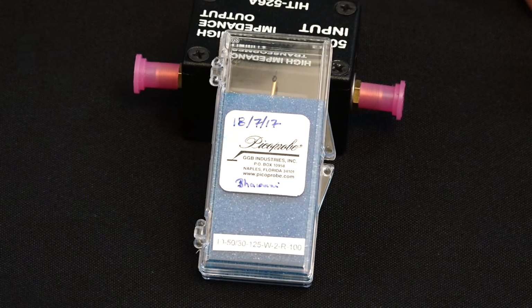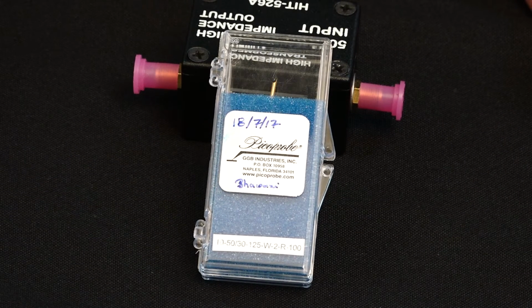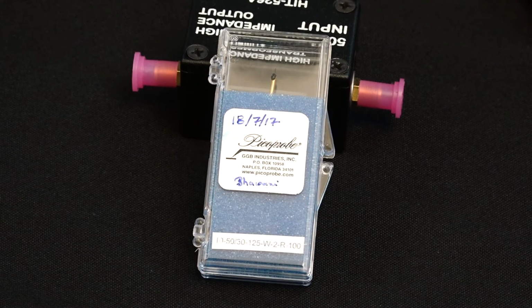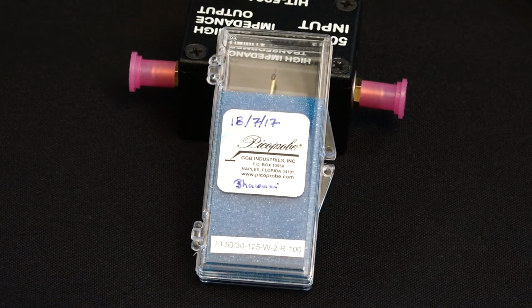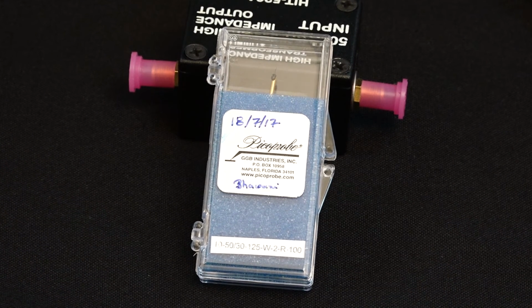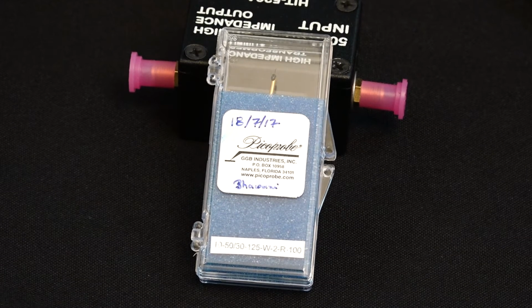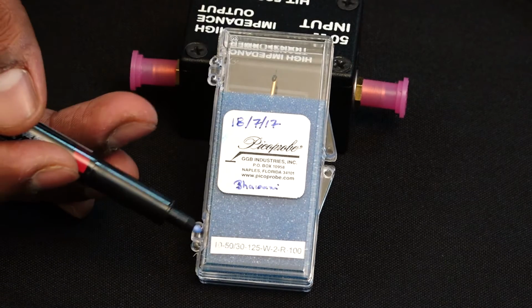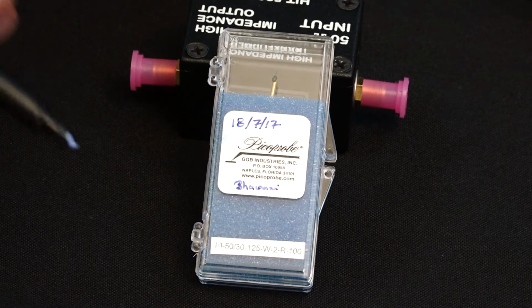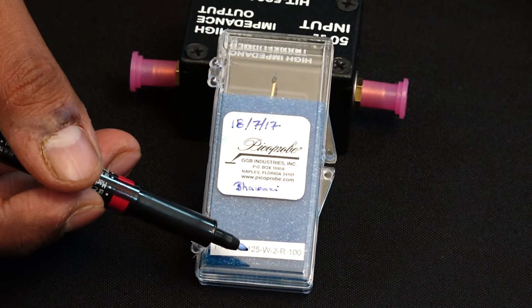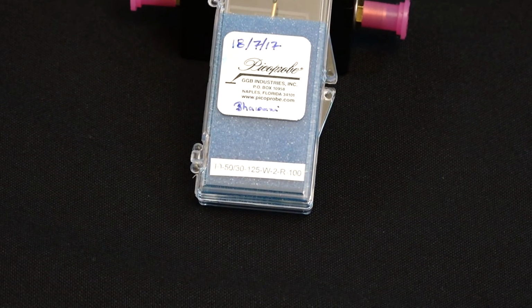The second set of numbers, 50 here, is the impedance of the probe. Every probe tip also has a certain impedance inside it, and if you remember, I was talking about a voltage divider network composed of resistors. That voltage divider network is also present inside a set of probe tips, so you don't actually have an explicit voltage divider network. This probe tip has an impedance of 50 ohm. Then the 125 here is the thickness of the probe wires that you can see. The two wires that we have have a diameter of 125 microns.